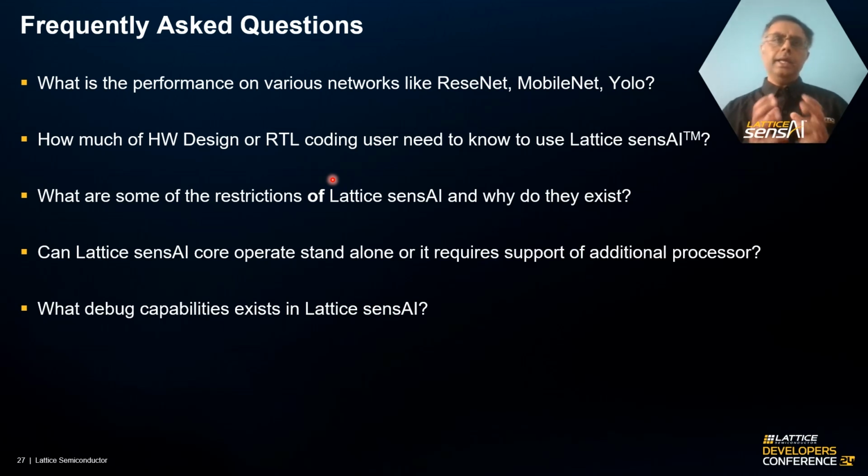Now, what are some of the restrictions of Lattice sensAI and why do they exist? Mainly there are restrictions in terms of the operators we support. It's not a generic neural network inference engine, it's a CNN inference engine, so CNN-based network operations are well supported. The reason is we want to create a very efficient inference engine.